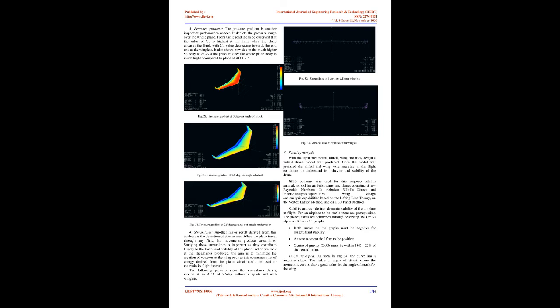1. Empennage design. Empennage design is the design of horizontal and vertical stabilizers with due consideration for lateral and longitudinal stability. As the name suggests, stabilizers affect the stability of the UAV, both lateral and longitudinal, in flight. The stability performance is defined in further detail in section 5.6.